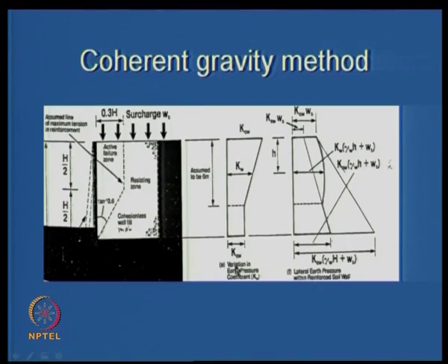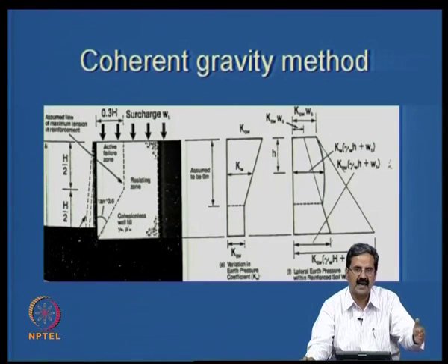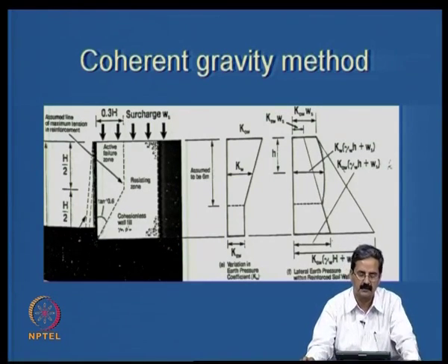Like I have measured. In fact, in one of the cases in Delhi, it's about 7 or 8 meters, but I was measuring with depth at some points. The earth pressure was K0. We have a measurement using some diaphragm. There is a method of measuring earth pressures. I used it and found that the earth pressure corresponds to the K0 condition, which means that the soil has not moved, like there is no lateral strain. That's the point.